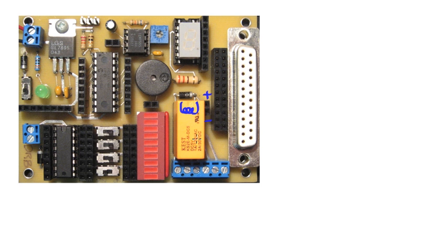Alright, so in order to control this relay, we simply have to provide a complete circuit. We've got to provide it because of the coil on here. It is designed for 5 volts, so we simply need to provide this with 5 volts and a ground connection. To control it with our microcontroller, you would think then we would simply take a wire from one of our ports and connect it to our positive, and take a wire from our negative and connect it over to one of our ground connections. Remember also that the first 4 on the left are our ground connections. The 4 to the right are our positive 5 volt connections.